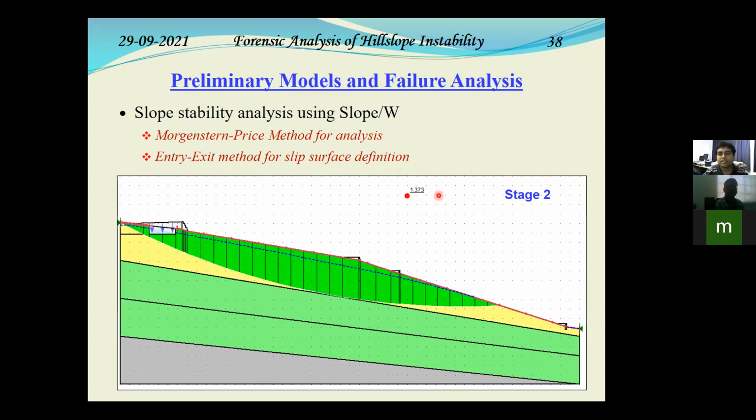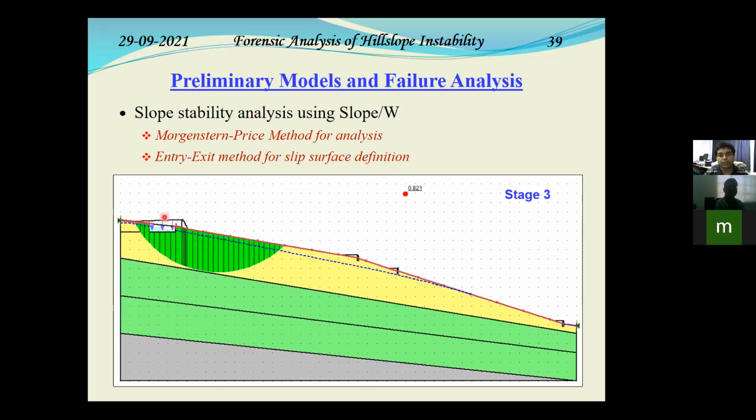So that means just the excavation did not start anything. However, when the building load started to get imposed, we could see that the failure factor of safety started coming below 1. Now in the field, any factor of safety below 1 means a complete failure. But in the field, what may happen is that the failure might have taken place partially, gradually things have started. So over the long run, probably it would have failed completely.